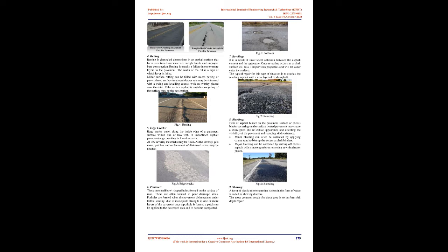5. Edge cracks. Edge cracks travel along the inside edge of a pavement surface within 1 or 2 feet. Edge cracking is found to occur in unconfined asphalt pavement. At low severity the cracks may be filled. As the severity gets more, patches and replacement of distressed areas may be needed.